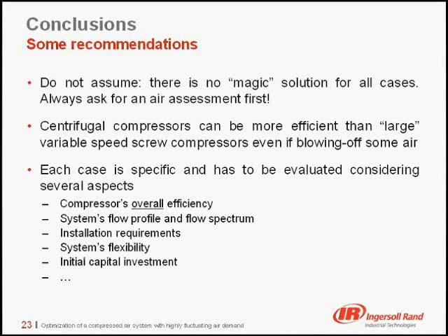which are compressor's overall efficiency, and with overall I mean not only at full load but also at partial loads, system's flow profile and flow spectrum, because it is fundamental to know how much time the compressor will work in one operating condition, for example close to the design condition, and how much time it will work in another condition, for example blowing off a little bit of air.